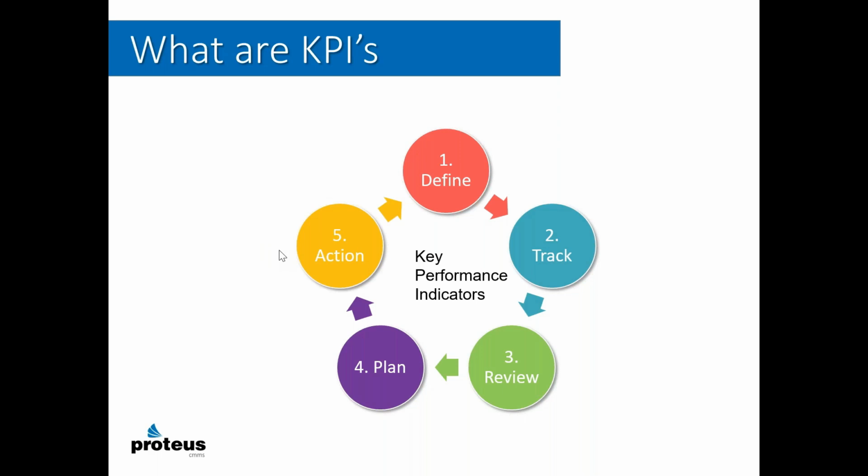But in this particular case, they had no system in place. So the next technician went in and replaced the thermostat. Then they got another hot cold call and they replaced the thermostat again. This happened 5 times in the same room at $75 a thermostat, and it wasn't the thermostat at all. It turned out there was a deeper issue causing the problem. So the value of KPIs comes in the review, the planning, and the action that you take with them.